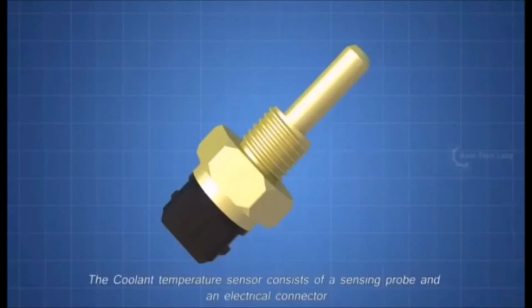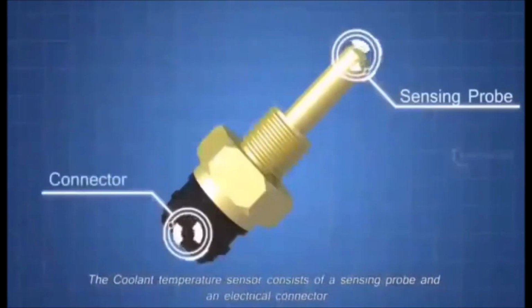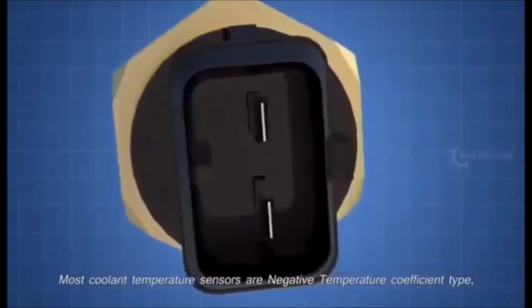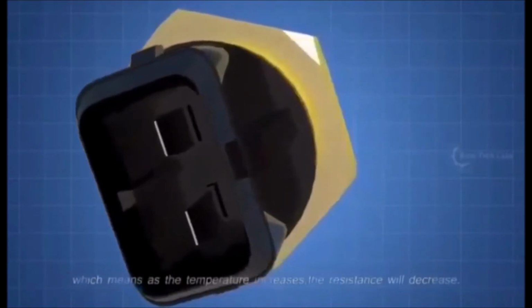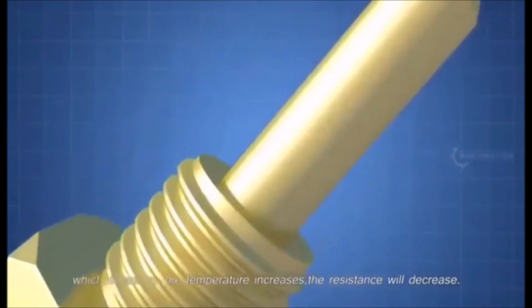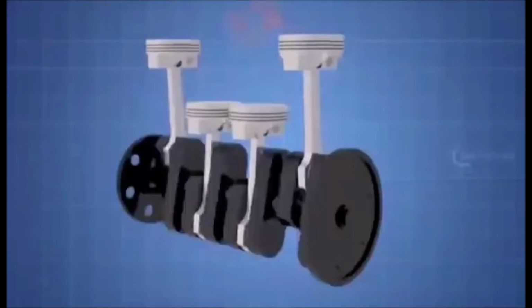The coolant temperature sensor consists of a sensing probe and an electrical connector. Most coolant temperature sensors are negative temperature coefficient type, which means as the temperature increases, the resistance will decrease. The CTS can be a 2-pin type, or a 3-pin type, depending on the make of the vehicle. These are the main